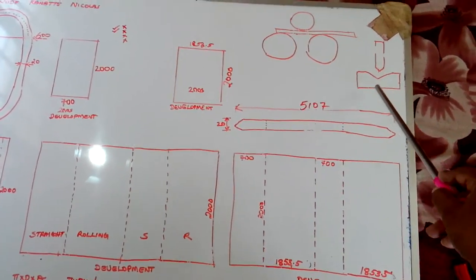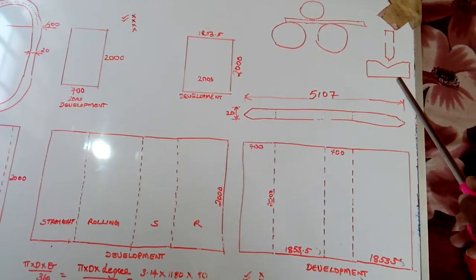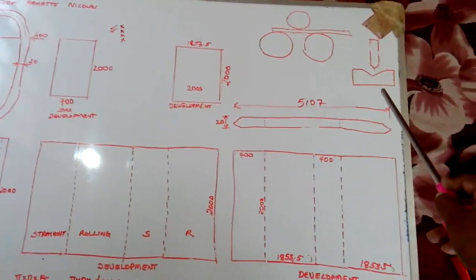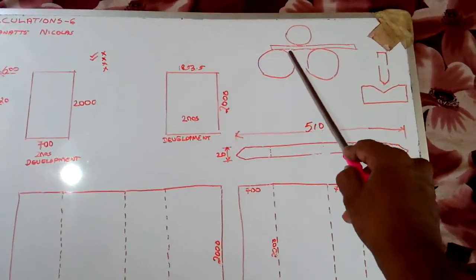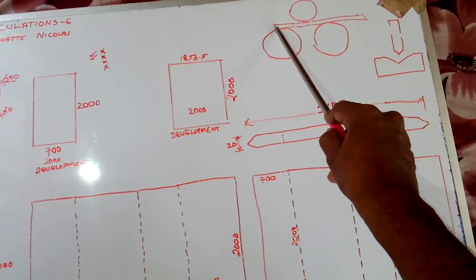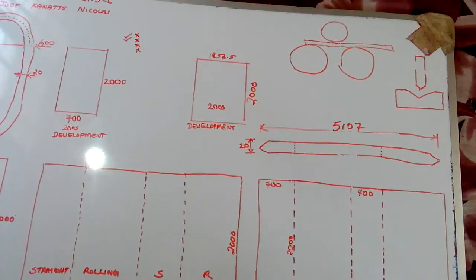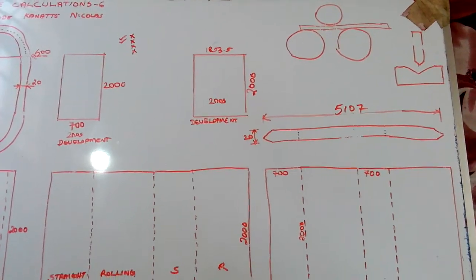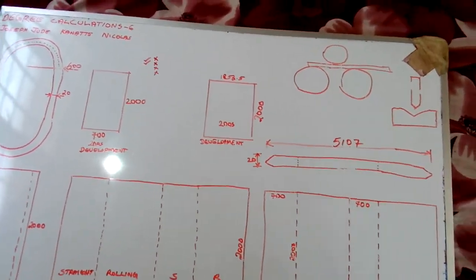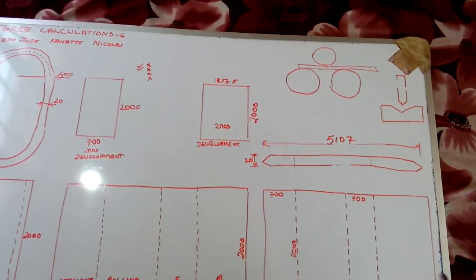If it has reached the proper radius, both ends have to be bent using the bending machine. Otherwise this portion of approximately 100 mm won't have a bend. Different types of rolling machines have different non-bending, non-rolling areas.